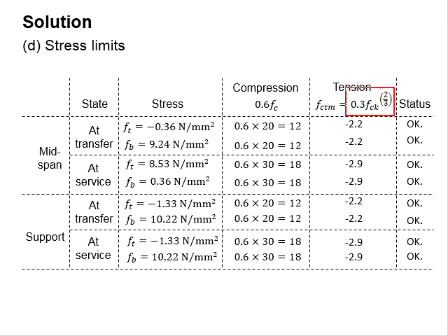This represents the equations for concrete strength smaller than 50 N per mm square. The value of fctm may be referred from Table 3.1 in Eurocode 2. It is a function of concrete strength, which at transfer is smaller, thus a smaller fctm is obtained.